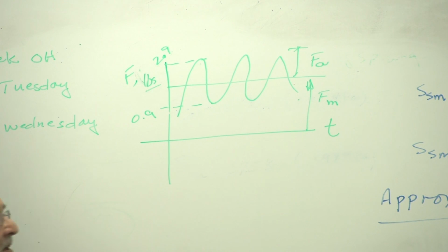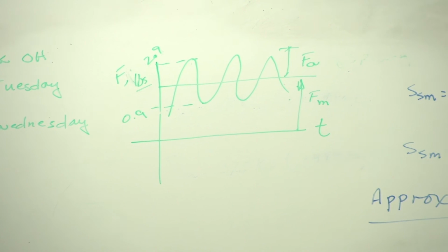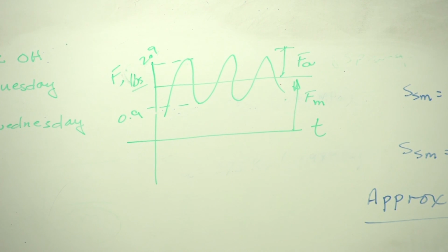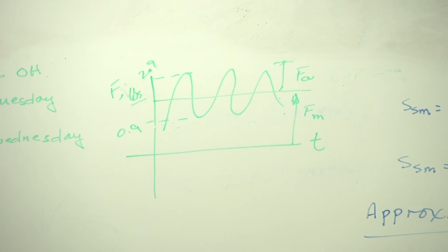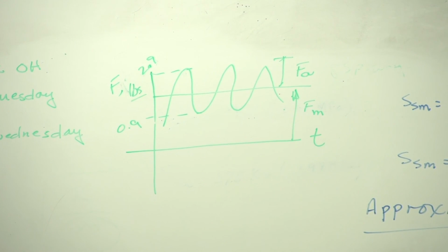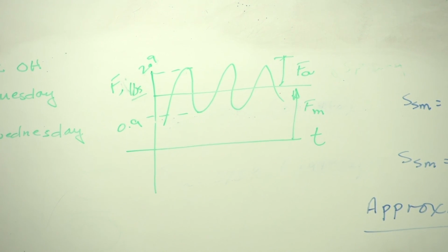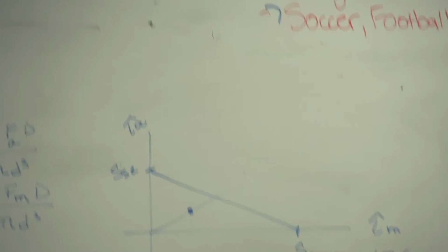And there's my alternating stress. And we do not worry about the preload. We will start our load line from 0, 0, rather than from some obscure location. So on this spring, check buckling, so long as we have the free length. Once you have the free length, that's when you should check buckling.